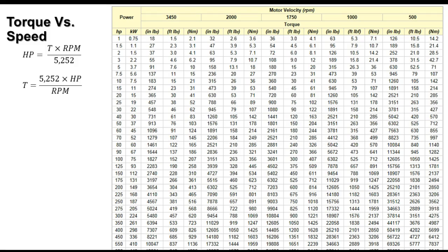So you can see the amount of torque you can get. Over here, we rate torque in foot-pounds. The rest of the world does use pounds. So we do inch-pounds or foot-pounds. But this is just a chart that gives you that. Now notice for the same horsepower, the actual work it does varies with what? What's across the top? RPM. Motor velocity.